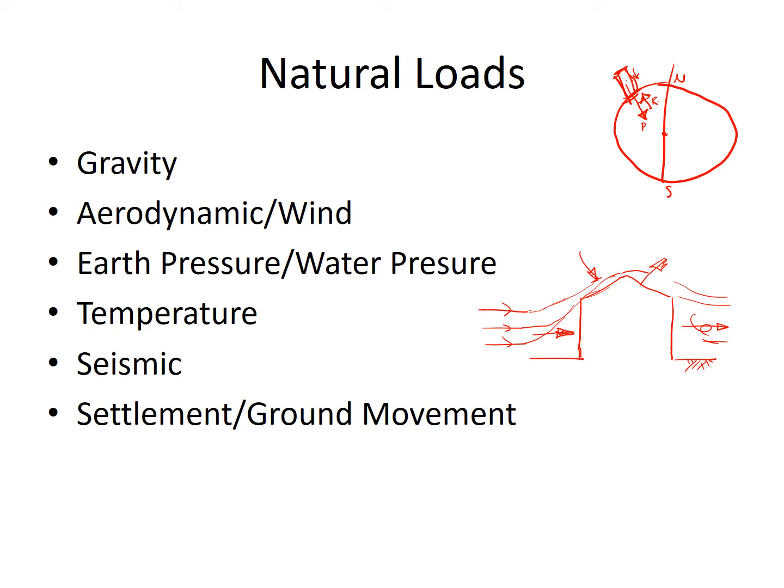Similarly, earth pressures and water pressures. If we have a pile of sand, granular material, that sits on the ground, that will have a natural angle of repose, which might be typically 30 degrees. And that is the angle at which the granular material can support itself. Now, if we choose to cut that natural slope at this point here by our building, so for example, if